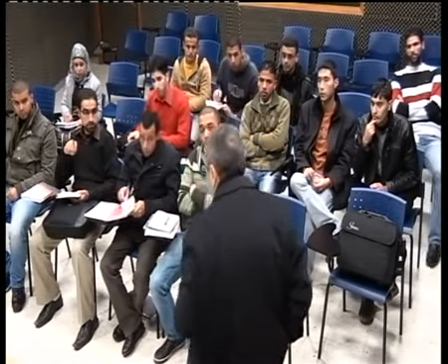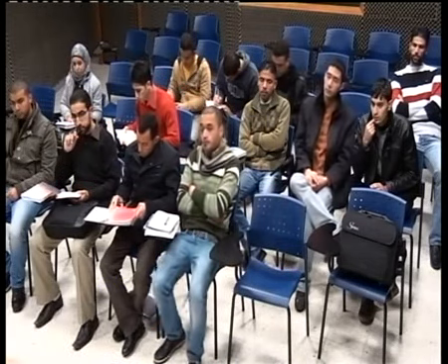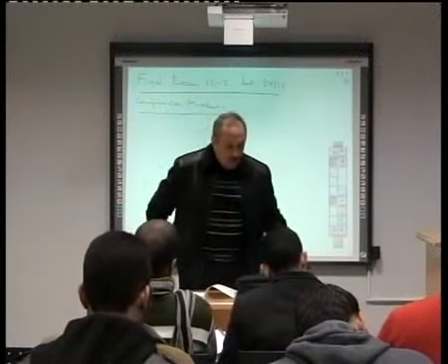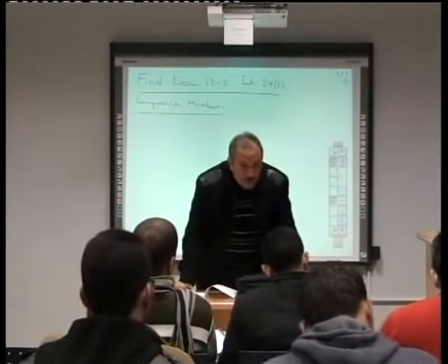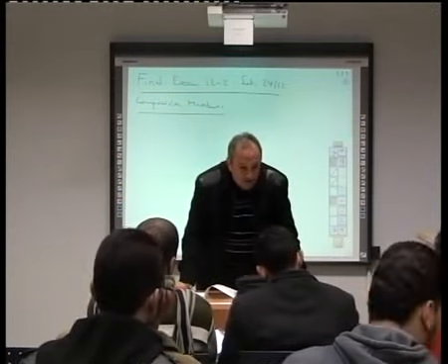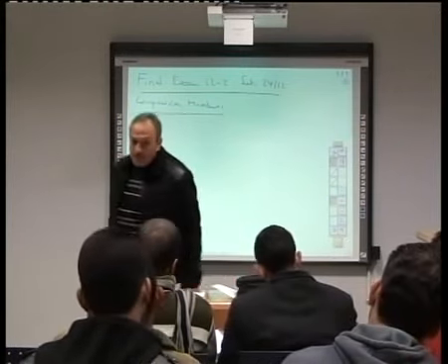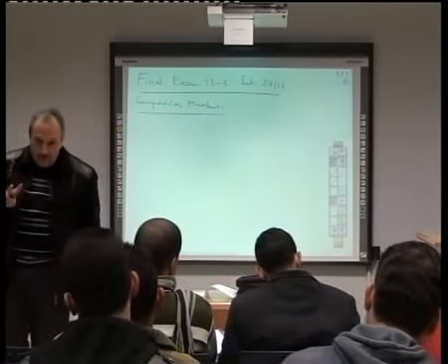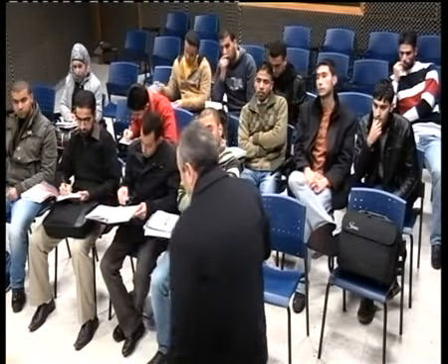Fracture, crushing, or buckling. So we have short members and short columns, and we have what? Long columns. But in steel, we can consider all columns to be what? Long. It's very rare that we find a short column. Now, buckling is the main item in design of compression members in steel. There are two types of buckling. One, overall buckling, and the other, local buckling.